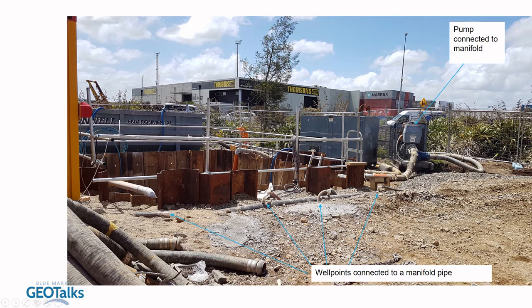In construction, excavation of open trenches below the water table often requires well pointing. This is where a line of wells are installed along the edge of a trench and water is pumped up. This pumping creates a cone of depression where the water table is lowered to provide the dry trench, but the cone extends well beyond the trench edge, and the process of dewatering can cause settlement of the surface as soil particles readjust due to the change from the saturated to unsaturated condition. This in turn can cause settlement of overlying structures that sit above the cone of depression.